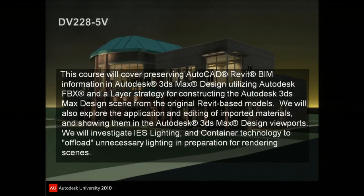I've also tagged this, we're going to explore the application and editing of imported materials and showing them in the viewports, but that's kind of been taken care of now because FBX 2011.3 actually fixed that problem. So the only thing you really have to do now is go in and turn on image-based. You just turn it on in the viewport and it comes in just fine now. Before, you had to recreate them. So we'll have a little bit of light discussion about that. We won't go in depth on it.